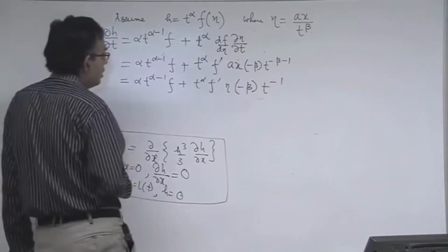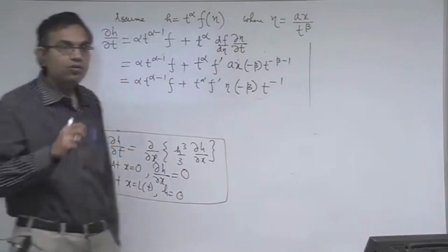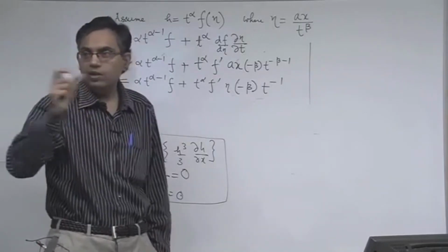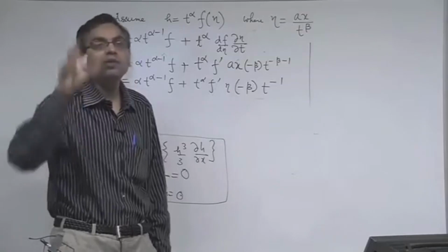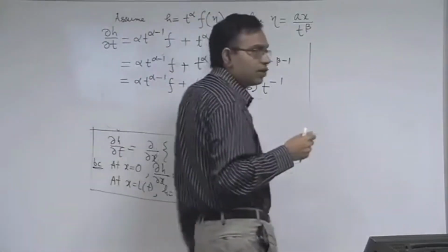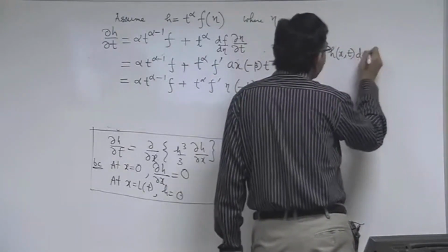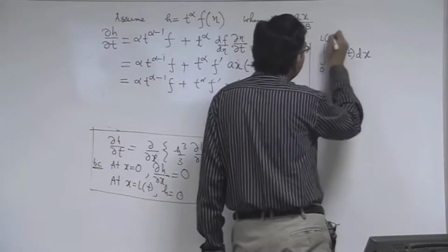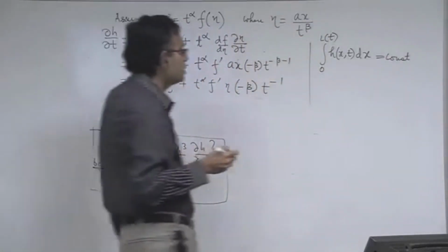Then there is a relationship between alpha and beta. This similarity will hold with a constraint of volume conservation, right. The h decreases and the L will increase in consistency with that, which we can say from intuition, because the volume of the droplet is conserved. If that is not conserved, you cannot tell anything about that. So volume of the droplet is conserved means the integral of h dx from x equal to 0 to x equal to L is constant. This is volume conservation.